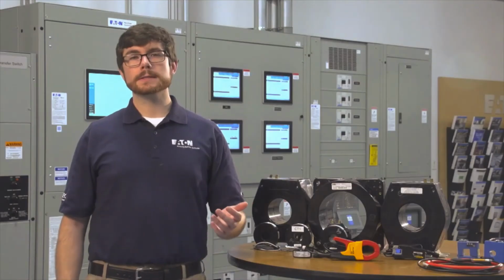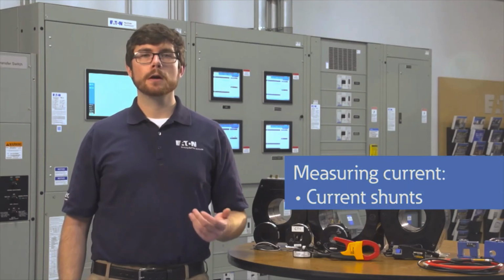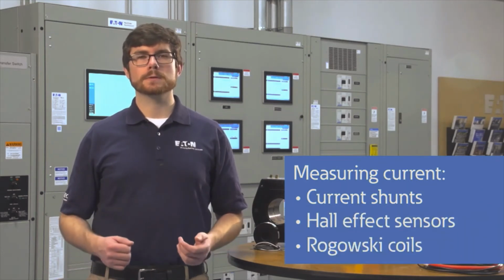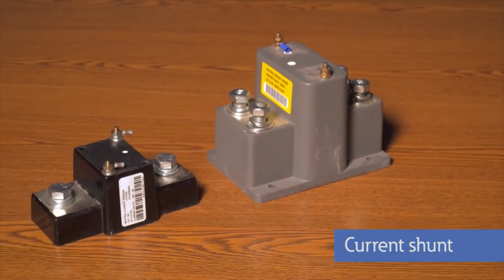The burden for today's modern electronic relaying and metering is very low compared to older equipment, but care must be taken to ensure CTs are not overloaded or inaccurate current measurements or protection will result. In addition to CTs, there are a few other ways of measuring current, including current shunts, Hall effect sensors, and Rogowski coils.